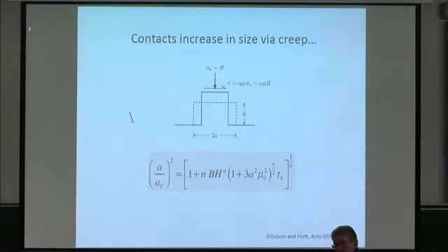So, to understand what's going on beyond that point, we think of an asperity, again in contact with its neighbor. I'm showing half a contact here, the other part above is not there. While holding, the asperity creeps. It shortens and it widens. As a result of widening, there's greater contact area, and upon subsequent sliding, the load or the shear stress required to continue sliding must go up. The greater the creep, the greater the area created, the greater the shear stress to be overcome to reenact sliding.